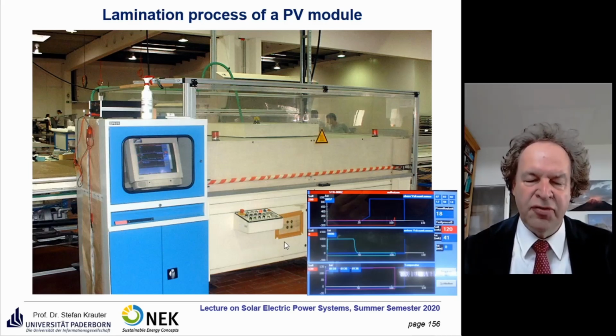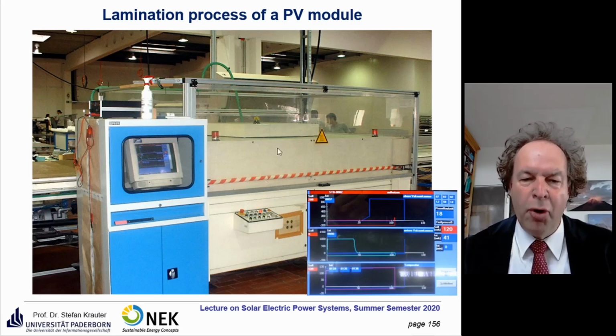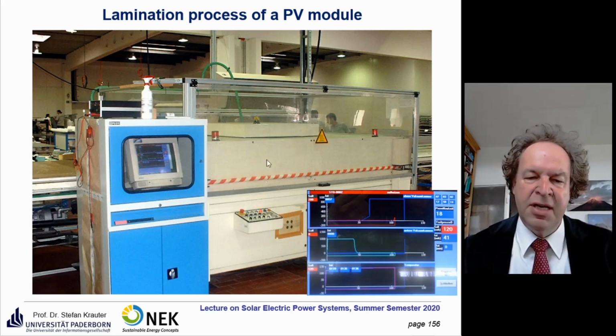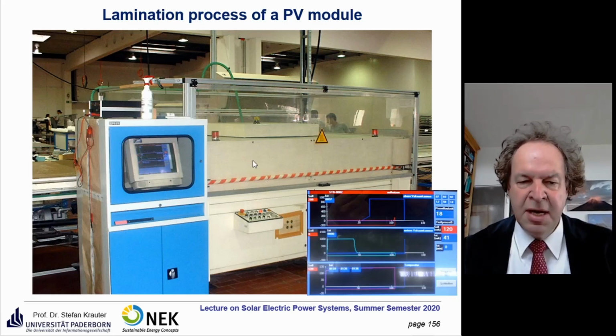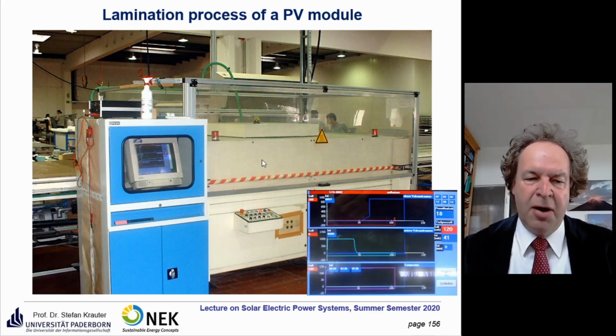It means the curing of the copolymer is carried out at different speeds. Sure, the super fast cure EVA is the most expensive, but on the other hand, you can produce more modules per hour within just a module factory. Typical temperature is around 156 degrees, and curing takes about 10 minutes. Sometimes you take them out of the laminator and they cure on their own in a curing room.